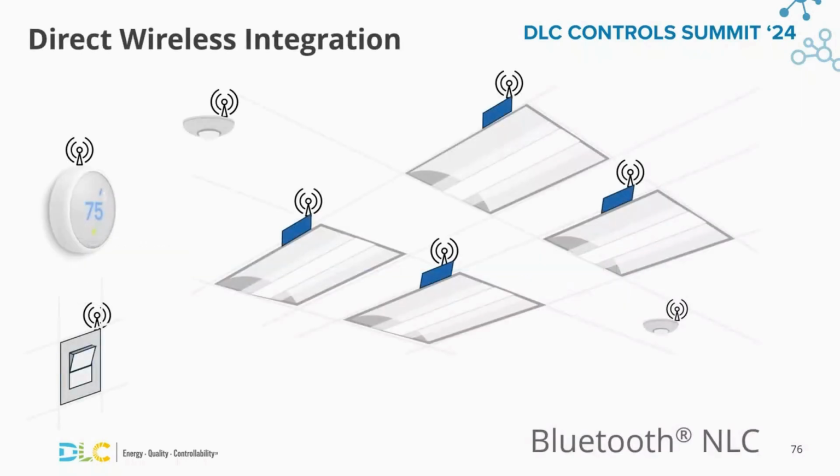A new method that is in development is to use an NLC system based on a Bluetooth mesh network to add a control node at the thermostat so the Bluetooth-enabled thermostat can read occupancy signals from within the lighting Bluetooth mesh network. Chris Walgamot at NIA is working on a project to demonstrate this idea, and the Bluetooth Special Interest Group is developing a new thermostat profile to match the recent Bluetooth NLC standard for mesh networks in lighting.